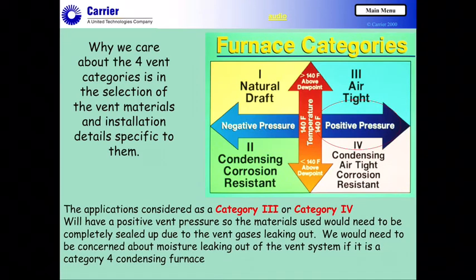Now, as I had mentioned earlier, these are positive vent pressures. So with positive vent pressures, whatever your vent system is, it needs to be sealed up. That might mean that you might be using a high temp silicone. You could be using some sort of, oftentimes they refer to that as RTV silicone. You might be taping your joints. It depends a little bit on that. It has to be able to handle the heat that would be associated with that.